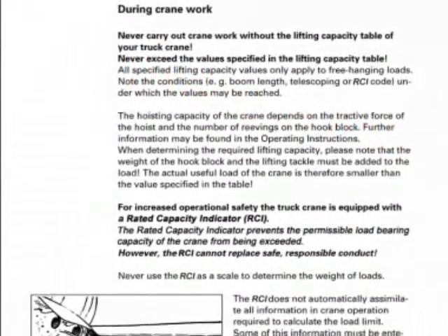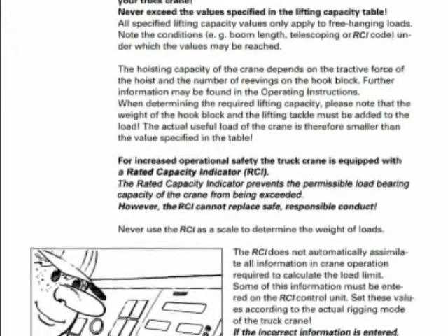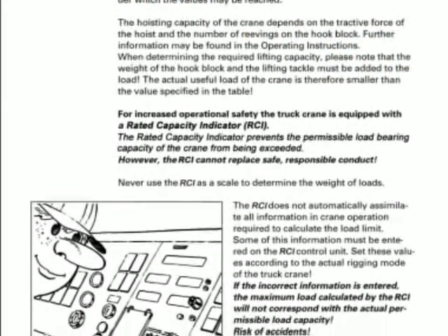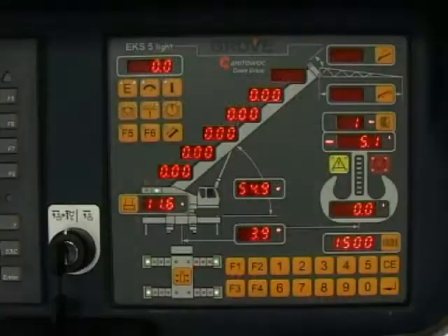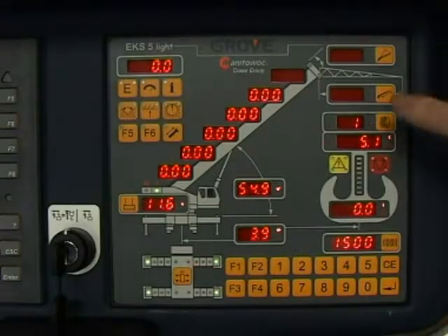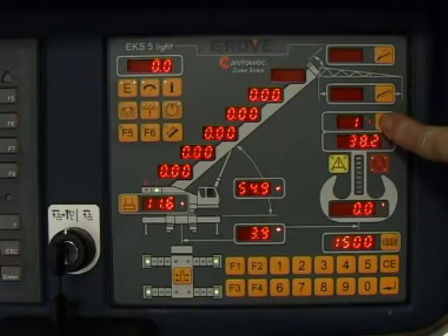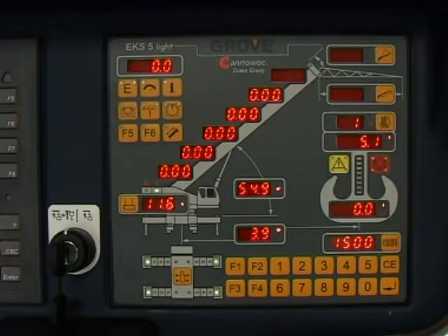You must fully understand the load chart manual and the conditions of use prior to operating the crane. Pressing the reeving input button will display the maximum load capacity for 3 seconds if the symbols flash to indicate load capacity reduction caused by insufficient reeving.